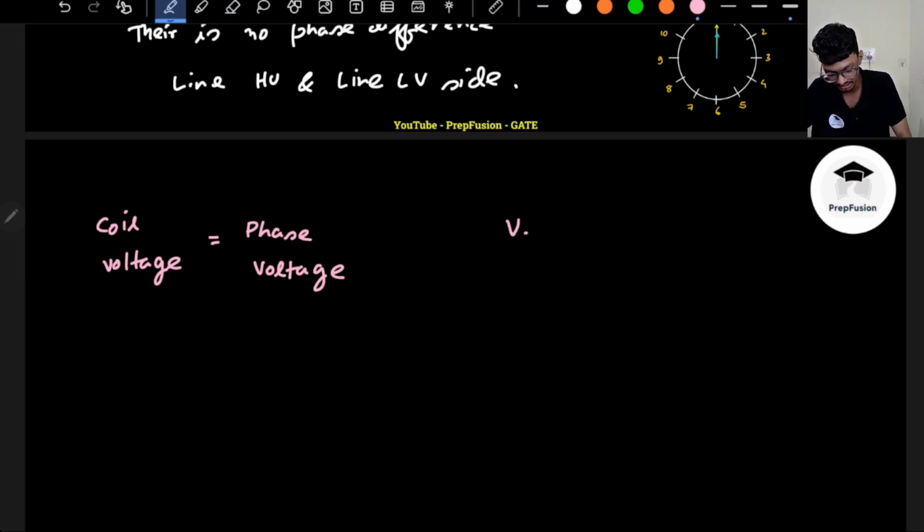Okay, point 1. Point 2 is, I know the phase voltage ratio. So basically I can say that voltage of phase A divided by capital A, it will be x basically, correct? 1 is to x, so it is x only. What about line voltages? So what is my line voltage VAB, capital AB? It will be root 3 times the phase voltage in magnitude. I am only discussing magnitude, phase we had already discussed.